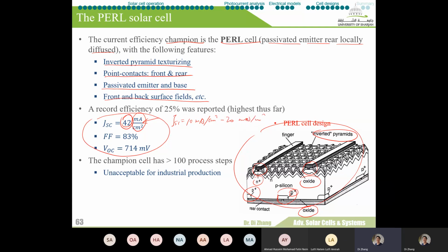For the newer perovskite solar cells, the short circuit current density can go from 15 to over 20, maybe less than 30. And for silicon, typically it has even higher performance. Here we're talking about 40, but it's also very common to see between 30 to 40 milliamp per centimeter squared for the current density.